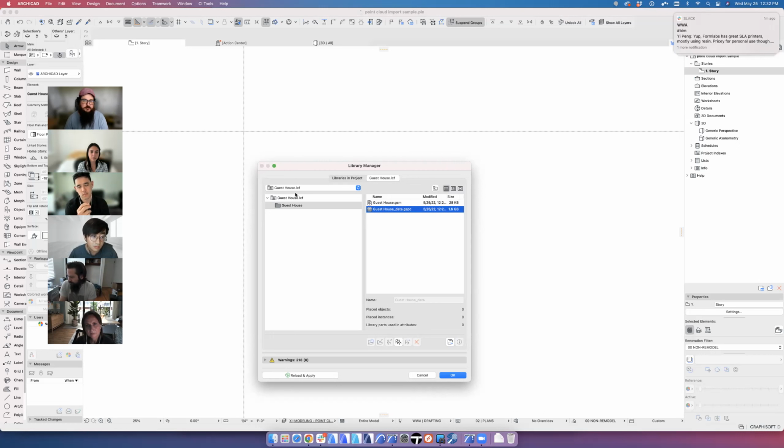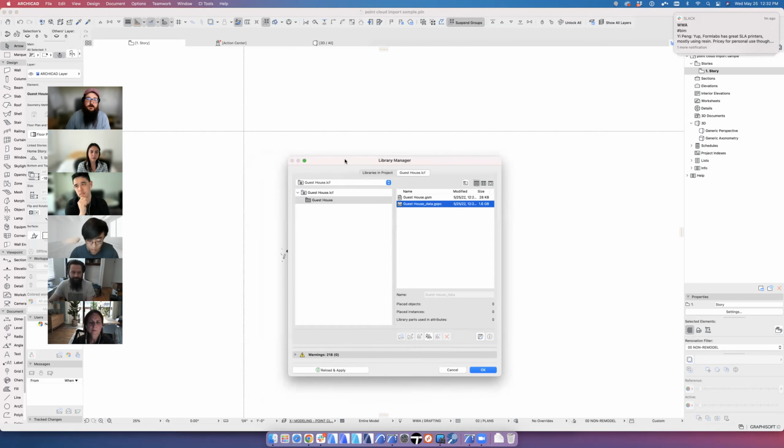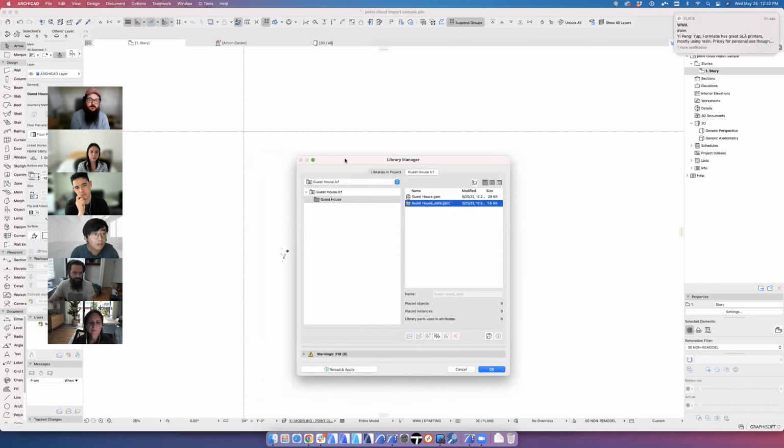We have a hard time with some of the projects staying below the 3 to 5 gig limit, and this would just kill one of those files. So do this work in a separate standalone file, a copy of the main working file, or just purge it out when you're done working and validating.